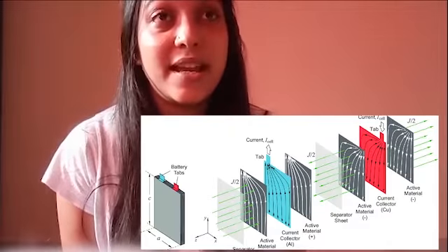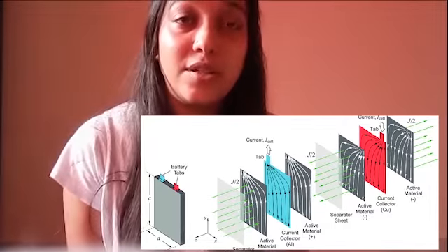The third step is pressing and splitting the cathode material on the copper foil, which is also called cold pressing and pre-cutting. The fourth step is cutting out the positive and negative electrodes of the battery, and the fifth step is finishing the prototype of the battery cell, which is also called winding. Now, removing the moisture and injecting the electrolyte is also called baking and injecting. This is the sixth step.